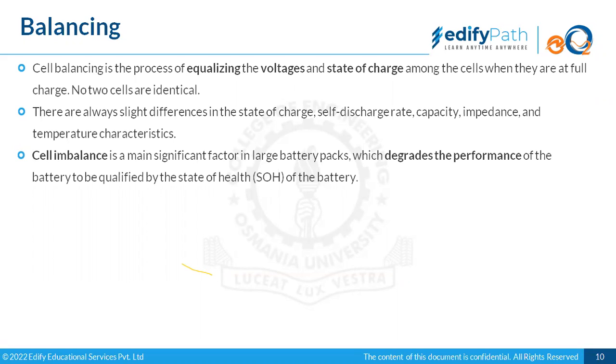The effect this has on the battery is lower range. A normal vehicle which was giving us 80 to 90 kilometers of range has now started giving a constant 50-60 kilometers. At times it could be because of road conditions or elevation, but when we feel the range has considerably depleted in say 100 or 200 cycles only, we would normally call it a disbalanced battery. In that case, we have to take it to the servicing station.